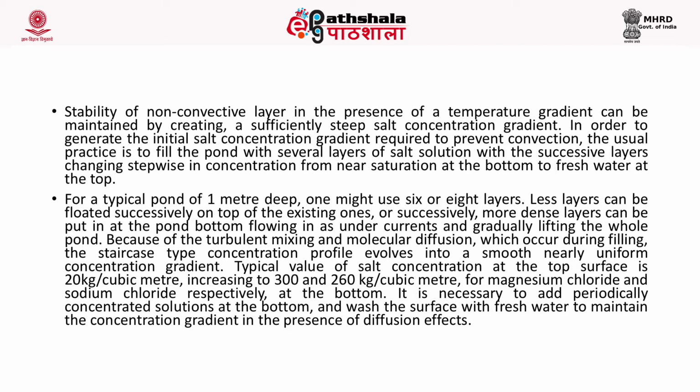Less dense layers can be floated successively on top of existing ones, or successively more dense layers can be put in at the bottom, at the pond bottom, flowing in as undercurrents and gradually lifting the whole pond. Because of the turbulent mixing and molecular diffusion which occur during filling, the staircase type concentration profile evolves into a smooth, nearly uniform concentration gradient.